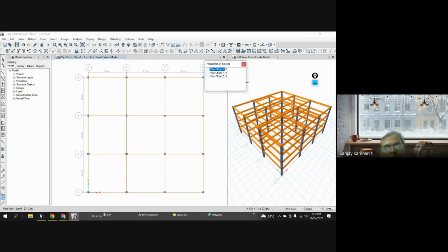see in point object, let us say in X direction, I want 2 meter on the right side. So I will say 2000 mm. Okay. In Y direction, I need 1.5 below. So I will say minus 1500 because that is in mm. Downwards means negative. Left means negative.